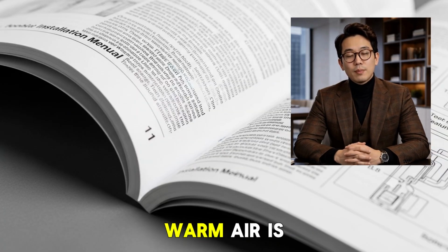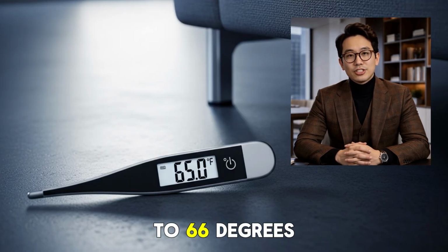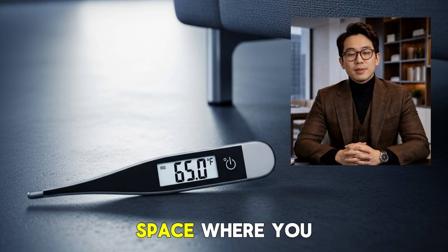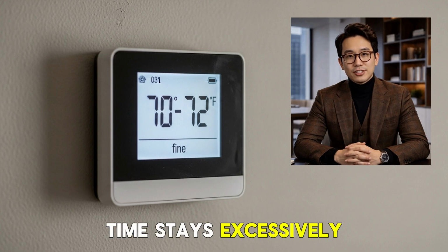Right now, warm air is rising to your ceiling and staying there. This is not opinion. This is physics. Hot air is less dense than cold air. Buoyancy drives it upward. In a room heated to 70 degrees, the air temperature at ceiling height can measure 78 to 82 degrees, while the air at floor level sits at 64 to 66 degrees. That 8 to 16 degree stratification means your living space, where you sit and stand, remains uncomfortably cool, while the upper 12 inches of your room, where nobody spends time, stays excessively warm.